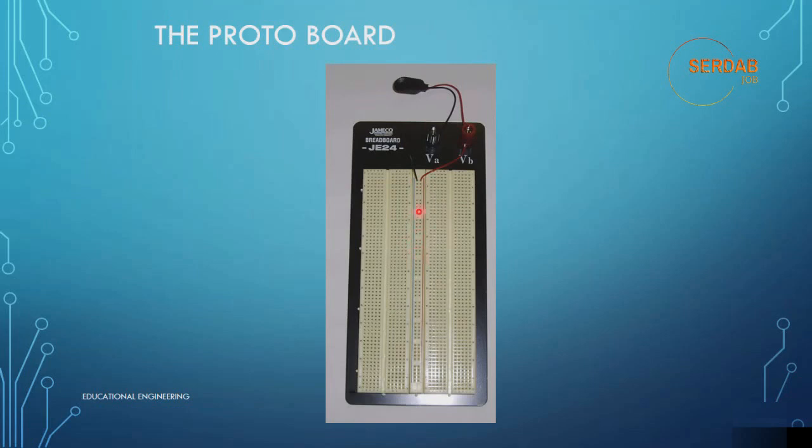If we connect them here, then all of these pins will get 9 volt. You can connect a LED to these pins, and you can connect a wire and take power from these pins, while the other pins here in that vertical line are connected to ground. So this is for connecting other circuit components here and here to power and ground, and it's a really useful board.